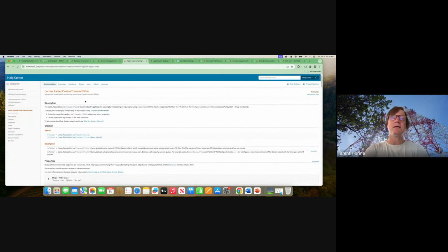Also, it turns out that these raised cosine filters and a lot of DSP processing in these types of radio systems use multi-rate processing, right? When you first started looking at sampled data systems, you defined a capital T, said that's your period. You have a sample rate, maybe F sub S, and you assume that that's constant throughout the system.